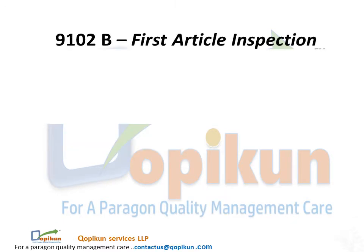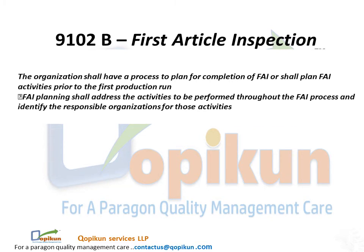9102B, first article inspection. The organization shall have a process to plan for completion of FAI, or shall plan FAI activities prior to the first production run. FAI planning shall address the activities to be performed throughout the FAI process and identify the responsible organizations for those activities.